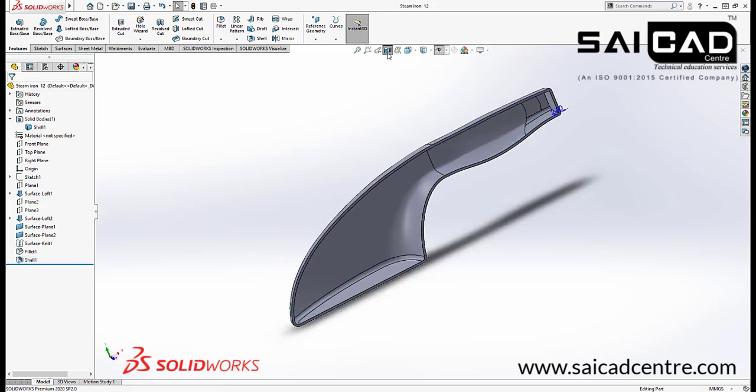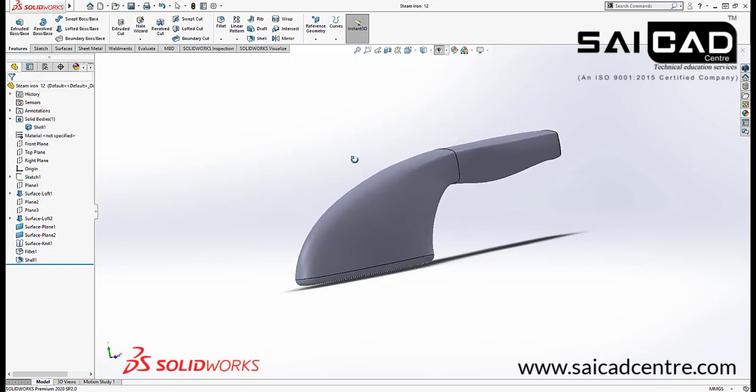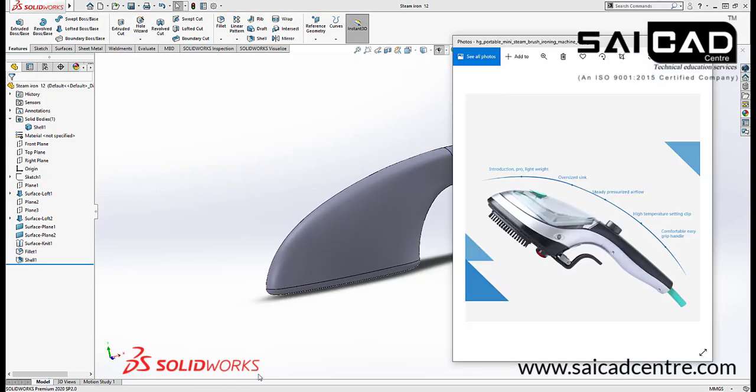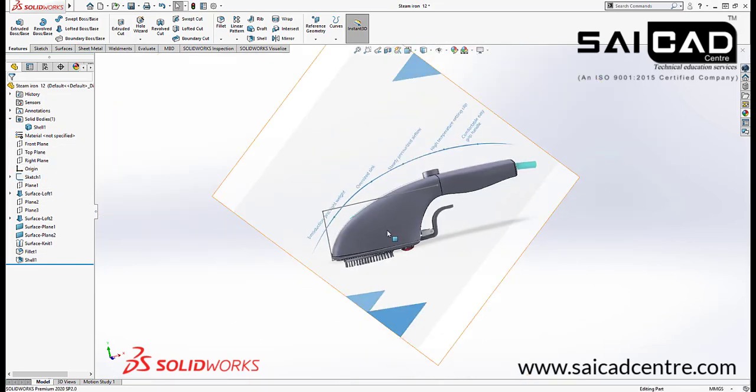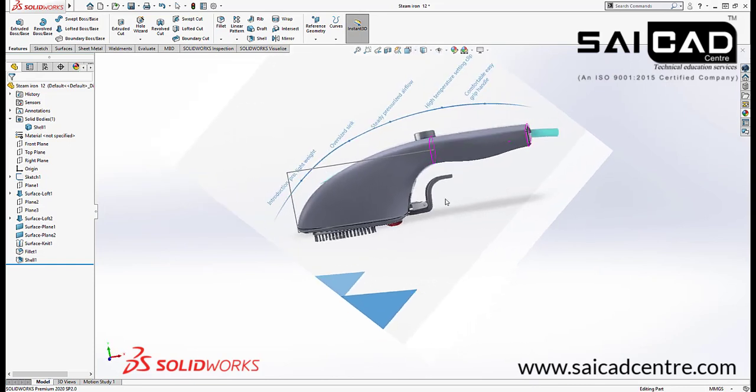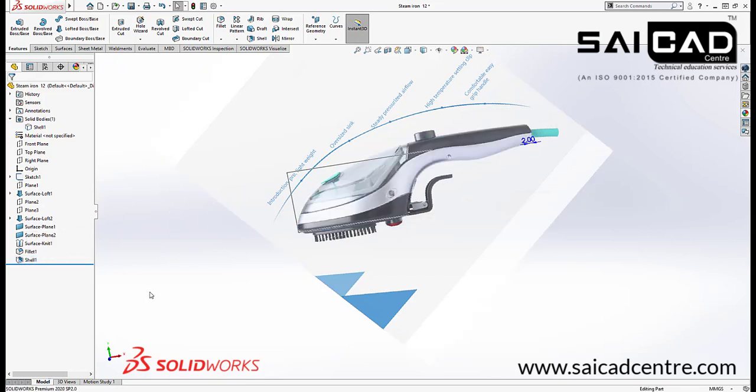Remove the option. Now we need to split the object, like we are having this in here. So in order to split it, we need to show the sketch so that we can get the shape. So now you can see we got the object here, we don't see our shape. So in order to do that, just hide it from here, hide the shell, and everything will be hidden.